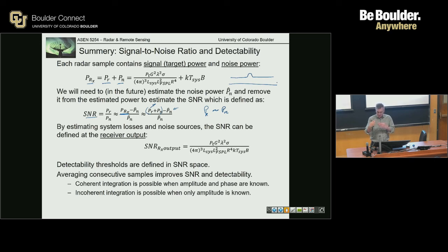If we then process 128 samples, then we're going to say the noise power is the summation of those 128 points. Then there's going to be some little sine wave that's varying. In the FFT process, it will pull that signal out.